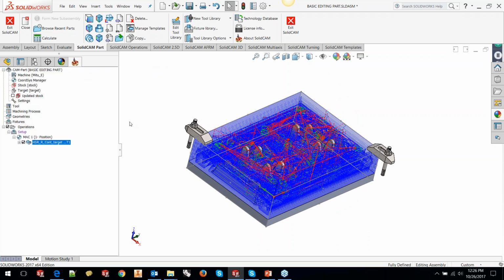Now, you would ask me, Amod, we already have toolpath editing. Why are you showing us a feature that requires another kind of trimming of the toolpath? The difference between toolpath editing and checking with fixture is that in toolpath editing, you're just removing a portion of the toolpath straight down. Whereas in fixture checking, what it basically does is it checks also your holder against the fixture, and it trims the toolpath in such a way that it takes care of your holder also, and it also takes care of those bolts and things coming out so that it doesn't collide when it's doing relinking.